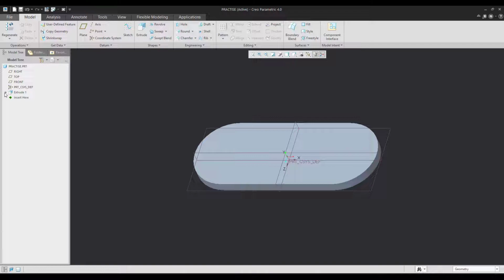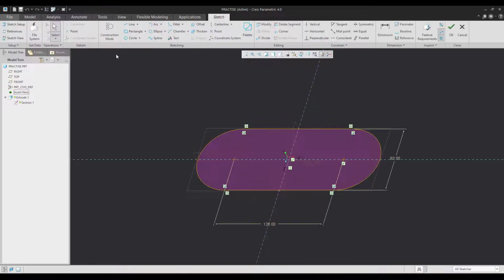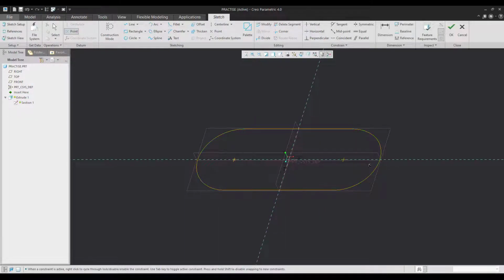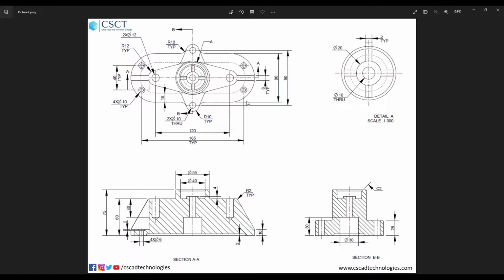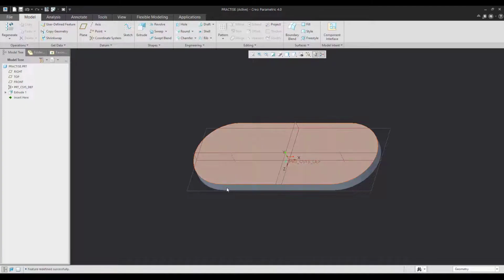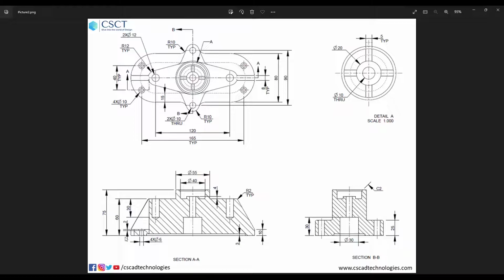For future references, I'd like to keep the axis inside this sketch using the datum point. I can use this axis later on for the other features in my model. The other profile is of this shape. Let me try to make this. The circle is actually of 55. So let me see the height of the feature first.